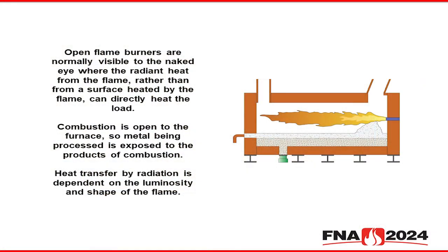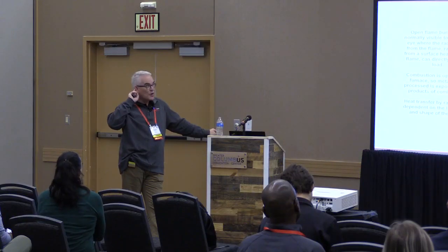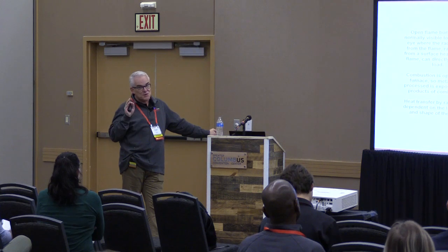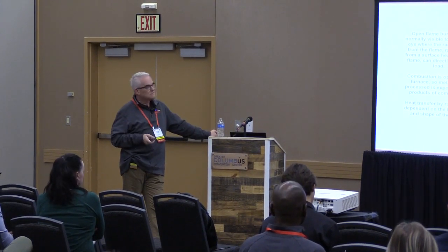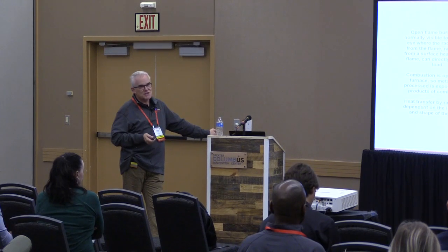Open flame burners, you can actually look in and see the flame, which again makes them a hell of a lot easier to tune if you're tuning to color. We don't recommend you tune by color, by the way. And we've actually met people who tune by sound. They listen to the open flame, and they can tell by the sound of the flame whether it's in tune or not. You've got to be really good to do that. The truth is you can't, but again, that's how some people do it.